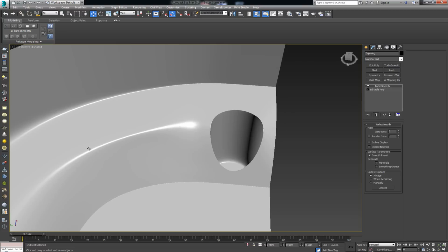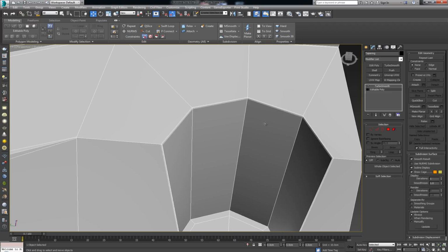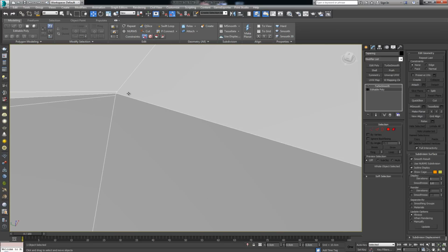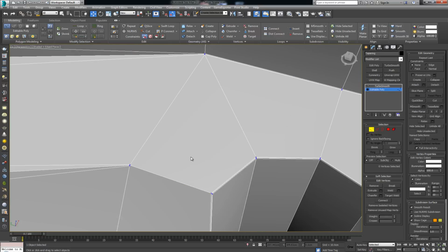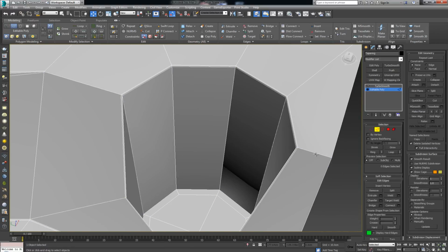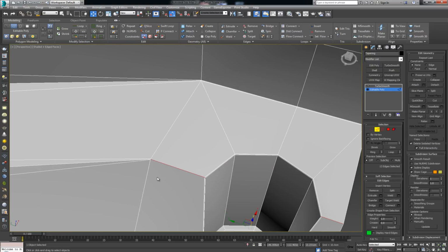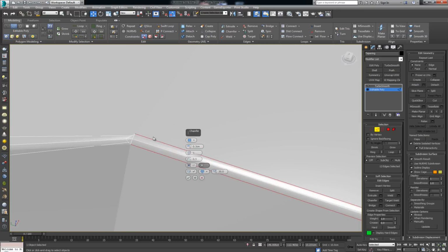So the problem is, how do we make this continue on to the other side? Well, if you remember, before I inserted this hole here, I actually went ahead and deleted both of these edges. So now, in fact, we have an end-on here. Now, if I simply continue this like so, and chamfer this, again, put it something like a smaller chamfer, 0.2, 0.2 should work.